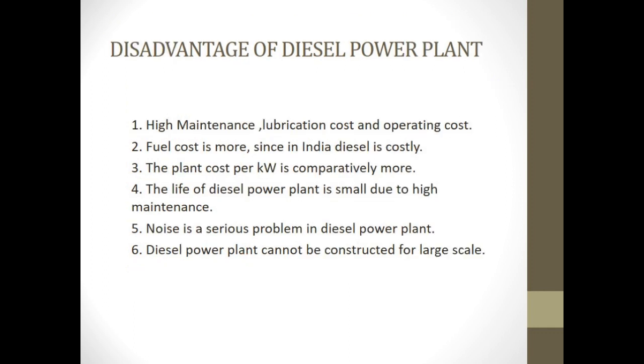Talking about the disadvantages of the diesel power plant: high maintenance, lubrication cost, and operating cost are required. Fuel cost is more since in India diesel is costly. The plant cost per kilowatt is comparatively more. The life of a diesel plant is small due to high maintenance. Noise is a serious problem in a diesel power plant. A diesel power plant cannot be constructed for a large scale. So these are some disadvantages of the diesel power plant.